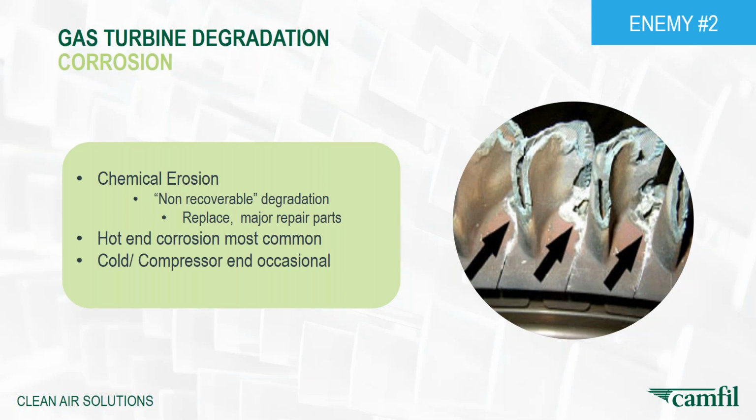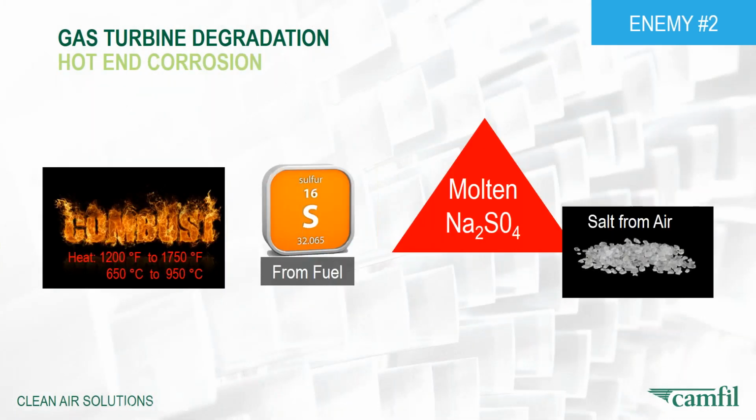For this discussion today, we're going to talk briefly, with one slide, on the causes of hot end corrosion. If anyone's interested, we have subject matter experts who can go into much more depth and detail regarding the various types of hot end corrosion. There are 4 elements to hot end corrosion. First and foremost is temperature, the heat up to 1,000 degrees Celsius.